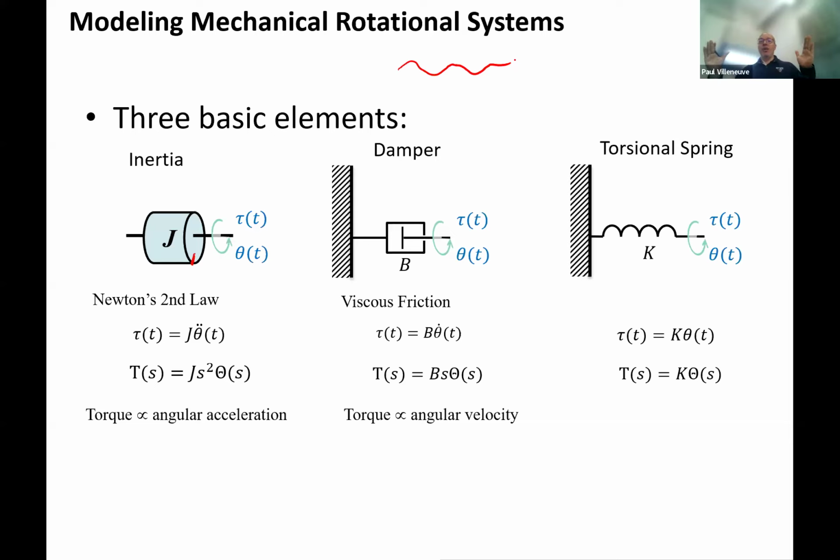They have ridges like that around the washers. And as you apply a force, as you rotate the object, you tend to move the shaft. It would move axially along the direction, one direction or the other. And it depends on how the motor is rotated or the unit is rotated. And that will push down on these things. And because that washer is a springy metal, those end up compressing. Okay. So they only will compress based on how much that shaft is being pushed against it. So that's the same thing as much as I move my position, we go ahead and move that.